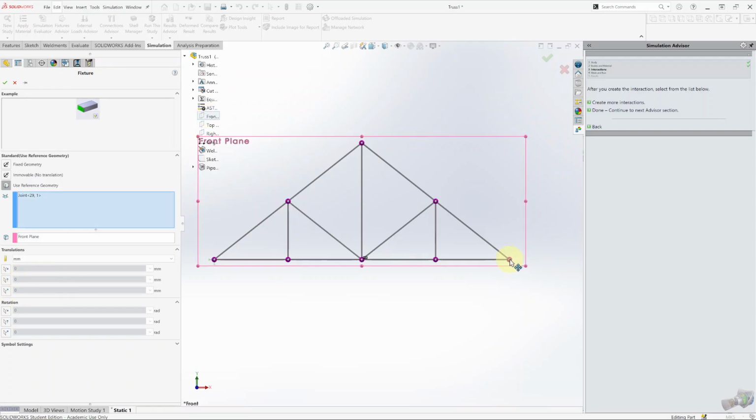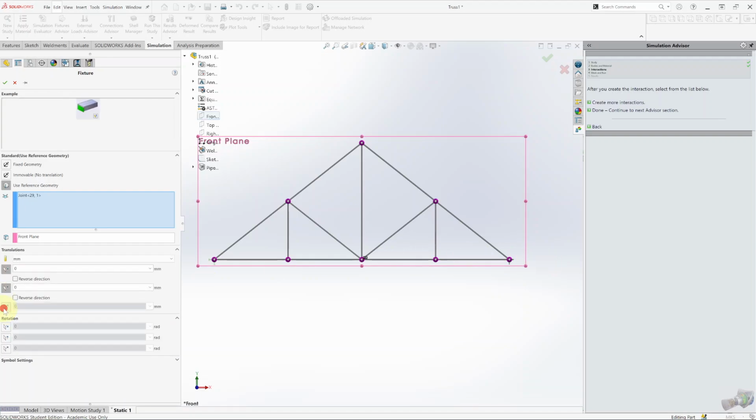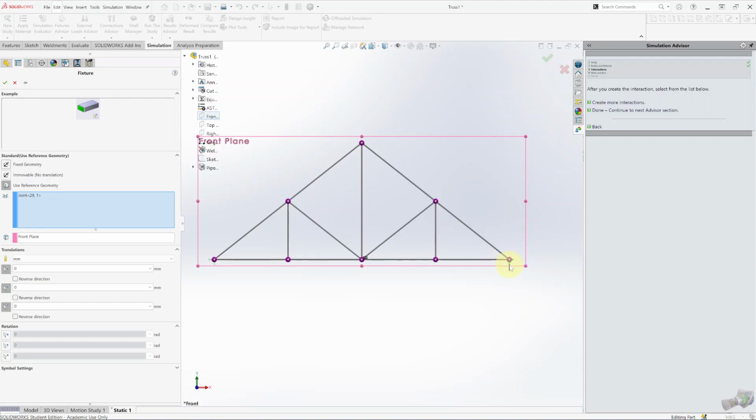And for this one, it's a pin connection. So now it can rotate about the axis Z, but it cannot translate on the x-axis. So it should be 0, 0, 0. We want to block all the translation at that point, and we want to block the rotation X and Y, but we want to leave free the rotation on Z. So this one at that point can only rotate about the Z-axis. That would be the same axis as my referential there.